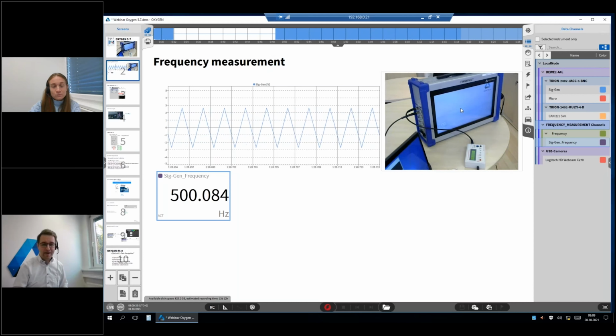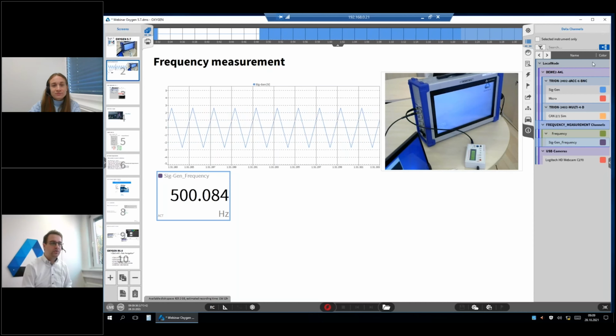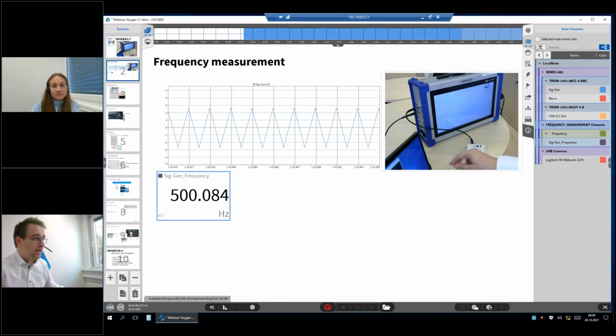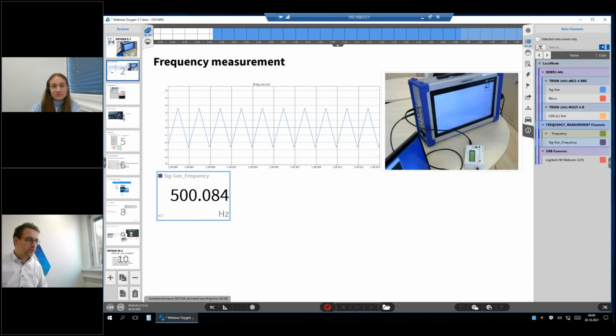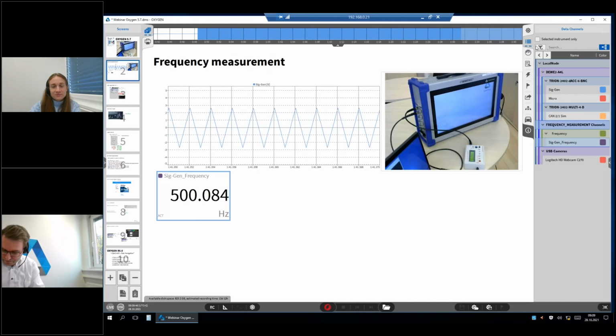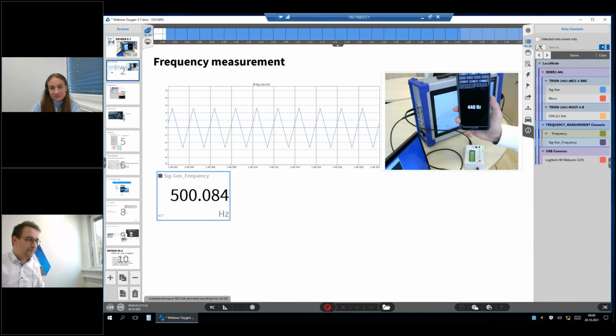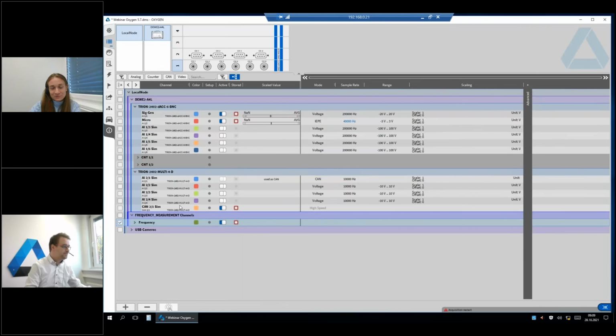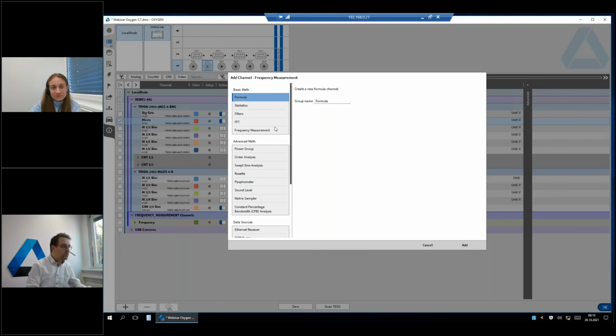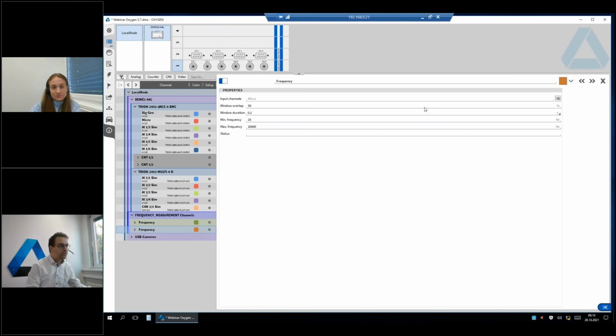And I thought maybe something different, maybe also something interesting to show is maybe a microphone. So what I'm going to do now is I have, as I said, a microphone connected here, as you can see, and a typical mobile phone where you can download over the App Store a so-called app, a simple tone generation app with 440 Hertz. And I'm going to take that microphone to show also that that's possible with a real sensor, and microphone is a real sensor. And I'm going to generate the measurement of the frequency for that microphone as well.